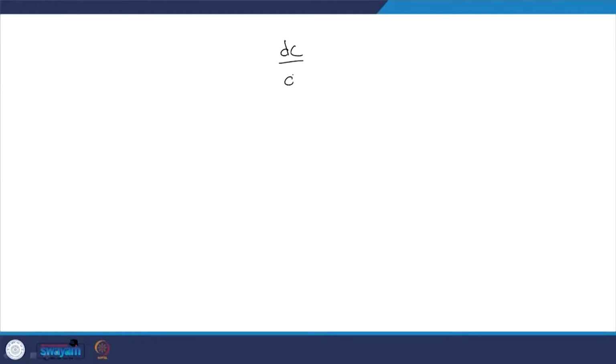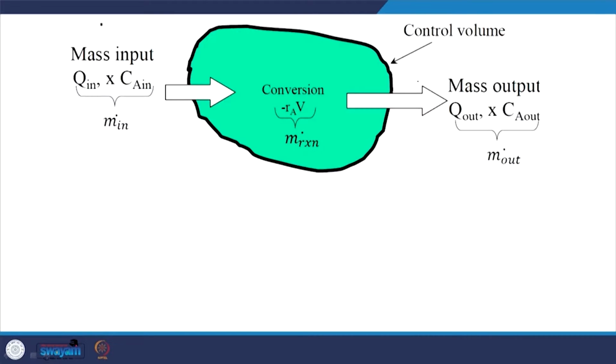In that context, we looked at the fundamental mass balance equation, and we see that we neglected diffusion and dispersion. So, the accumulation term plus u dc by dx, which is due to advection, the concentration change with distance, is going to be equal to rate of formation minus rate of loss of the particular compound. This is the fundamental mass balance equation, neglecting diffusion and dispersion. So, we will try to understand the mass balance in the usual way too. We looked at the fundamental mass balance equation.